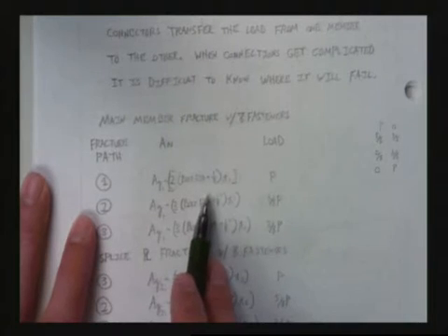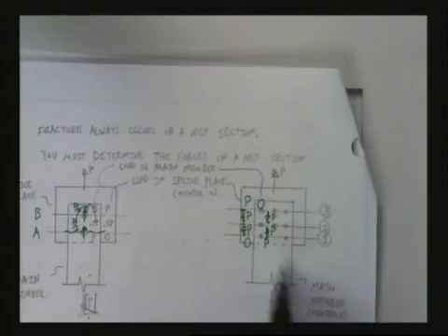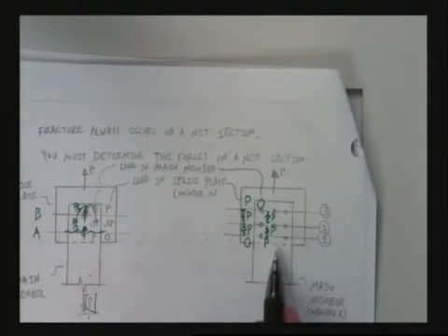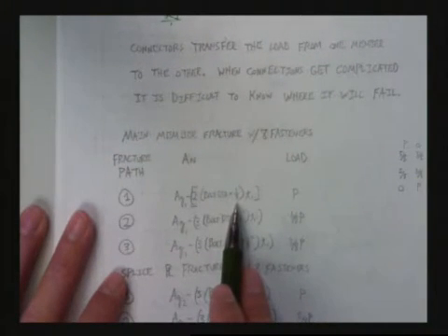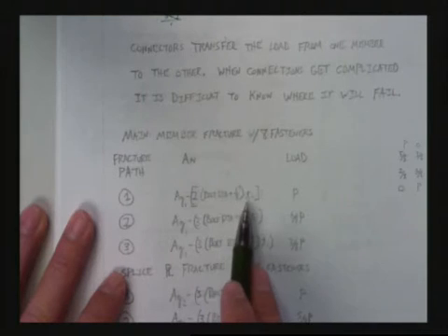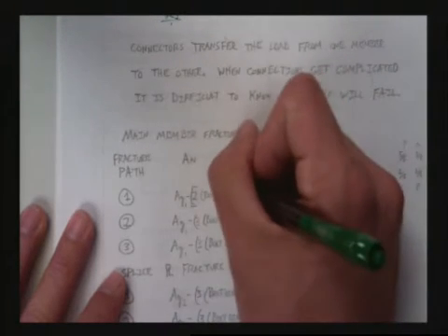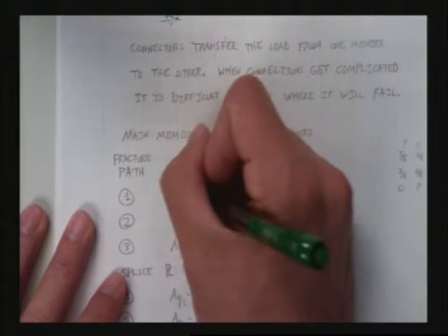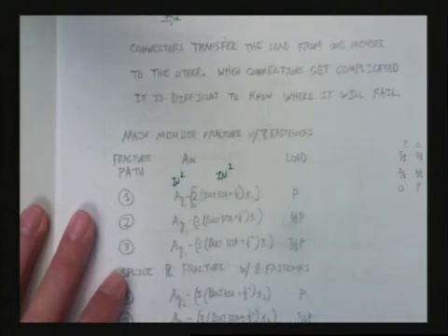Why do I do that? Because there's 2 bolts, right? And then why do I add 1/8? Slop. And then why do I multiply by the thickness? Because you got to get an area. You got to check your units. You need inches squared here, and you need inches squared here, right?